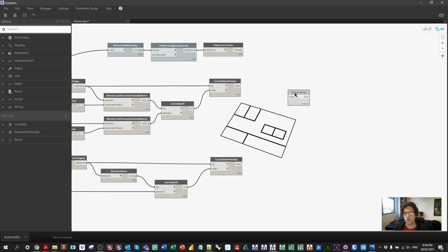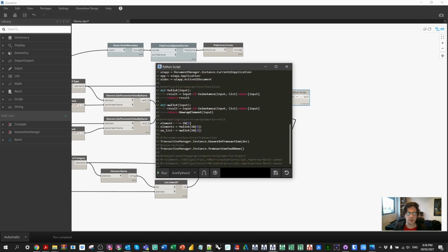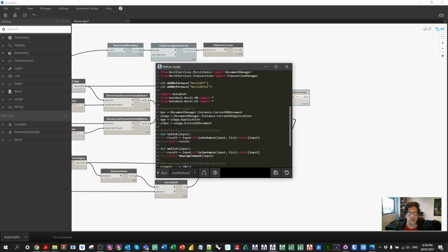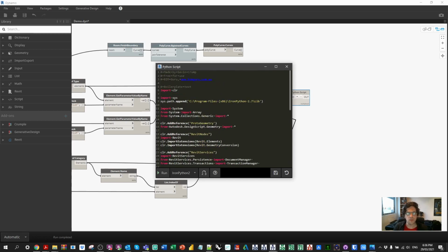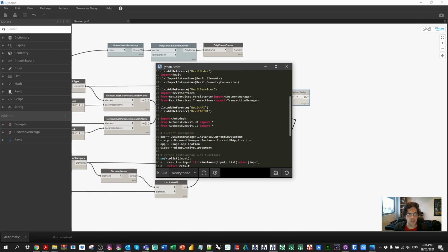It's important to note that if you do want the same Python contents in your node as me, go to my GitHub and you'll find this same template available for you to begin from. Noting in this case as well that sometimes, depending on which version of Python you're using or which version of Dynamo, you'll get different syntax for how the tabs are managed. So notice in this case, the tabs in my file are managed using 4 dots. So you will have to be careful that you're consistent with either using tabs or 4 dots. In this case, if I do a tab by default, notice it's actually a tab. So what you may wish to do is replace some of these elements with tabs, just so you can begin using proper tab formatting. I believe this is a fairly new feature to Dynamo.